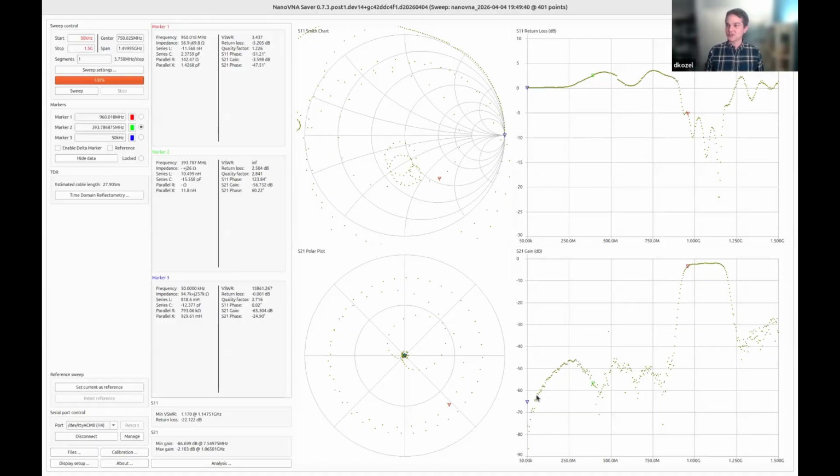Looking at the S11 return loss, I know that I cannot possibly be getting more power back than I sent, I can't be getting an active signal back. I would not believe the S11 return loss, so I'd have to go back and recalibrate this and retest the measurement. Either that, or I'm having presenter head and I've flipped my negatives.